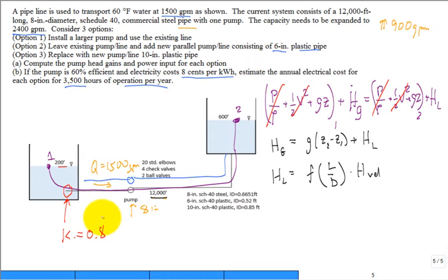He sent me an email this week or last week and said he's doing piping calculations and designing for moving product in the Houston area and South Texas area. And he uses the Crane manual. That's his go-to standard for calculating head losses.